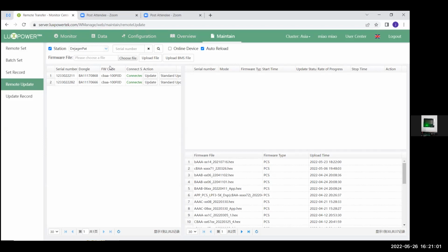And it is advised to update your inverters to the newest software when you install the parallel system, because the newer firmware has a lot of fixes for small bugs that were in the firmware on the older versions. So it's always advisable to upgrade your firmware to the same version. So that's basically for the monitoring page, what you have to do to get your units together.